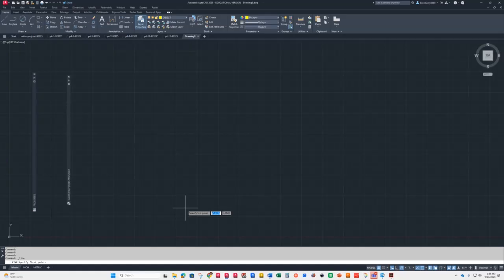Now, line type scale, I could go ahead and tell you, is probably going to be smaller on this one. Since we don't have to change our limits on this one, it'll be fine. There's plenty enough space for it. Then I am going to change my line type scale after I hit escape and get back into that, LTS, and I'm going to make it 0.5.